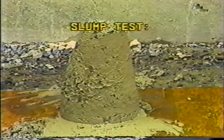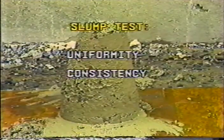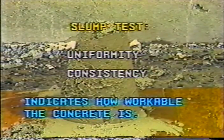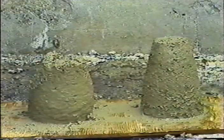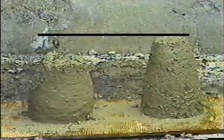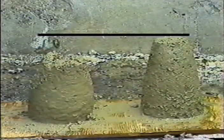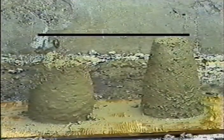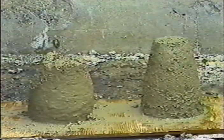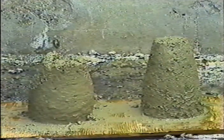The slump test is a measure of 2 things: uniformity and consistency, and it indicates how workable the concrete is, whether it's relatively stiff or more fluid. Here are 2 examples with different slumps. It's a bit confusing to beginners, but you'd refer to the one on the left as having a high slump. The one on the right has a low slump. When you think about it, it makes sense. The concrete on the left slumped farther, so it has a high slump measurement.